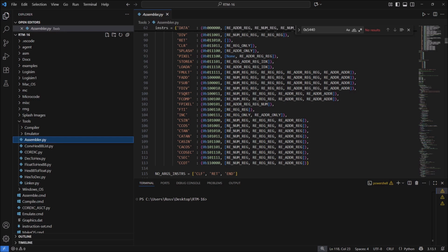We're going to have 3 different addressing modes. One will be a number to a register. So that addressing mode was what we saw whenever we generated the sine function. We had a number, and the value was then held in a particular register. We also get the register to register, so it means that the number that we're looking for already exists within a register. Okay, so register R0 would contain, say, the angle 45 degrees, and it would return it to register R1, which would be the sine of 45.